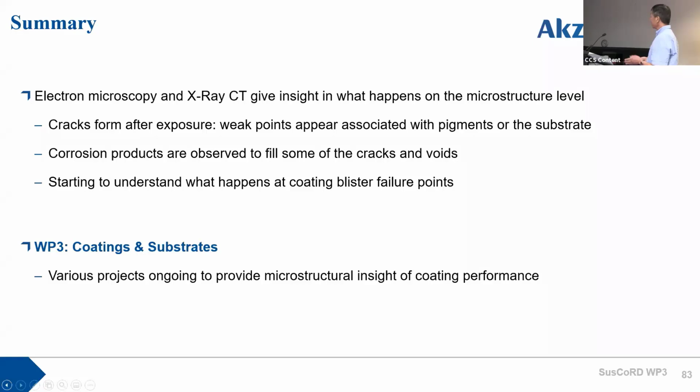Also, Stuart just mentioned that good adhesion does not necessarily mean good performance. I slightly disagree with that, because for certain systems adhesion is important. For example, if you have a substrate with a certain microstructure feature that is sensitive to the environment, so that only this part of the microstructure exposed to the electrolyte can corrode, then adhesion is important. If you have good adhesion, that means the interface is protected, and you prevent that susceptible microstructure from being exposed to the environment.